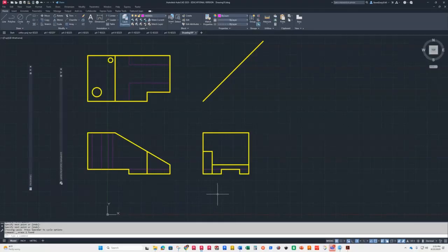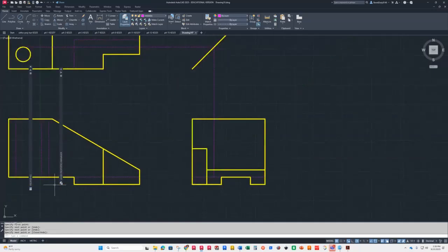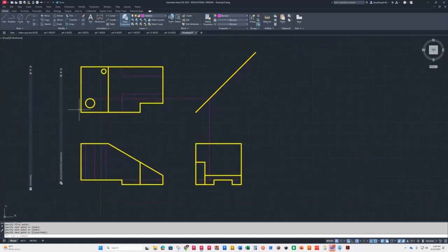It's fine. So I still need to put my hidden lines for the holes. Now, it's very important that when you put these in, you remember that they only come down to the hidden line. They don't go all the way down through here, because if you look over here, they're over where this is up, right? So it's even with the hidden line here, which would be the same as this hidden line. So they only go down to there. And let's see, draw a line.